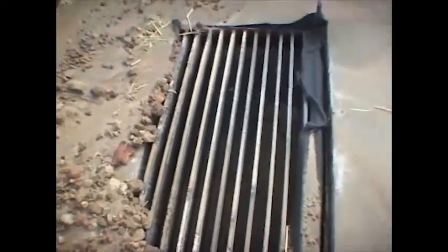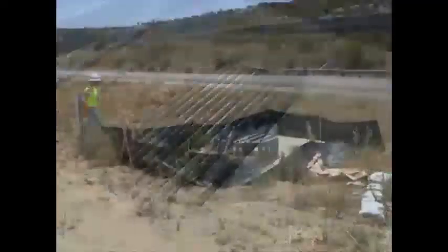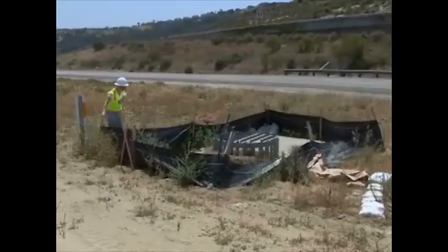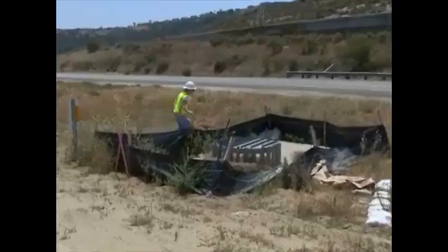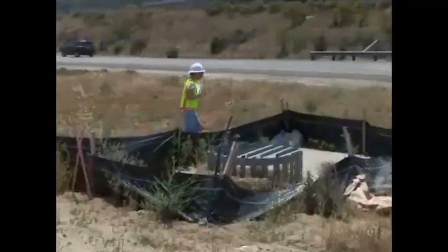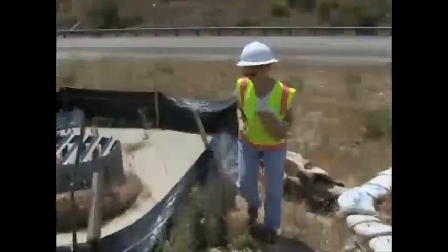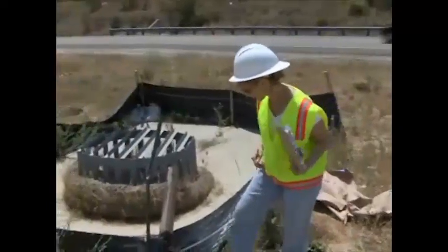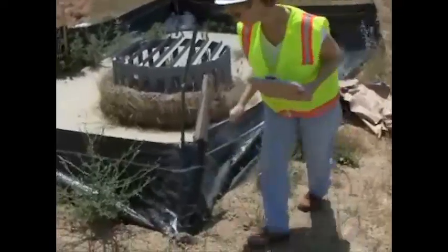If accumulated sediment has reached 1/3 the holding capacity of the device, then make a note of it and ensure that it is removed. Check and ensure that the stakes are securely driven into the ground and are in good shape, not bent, cracked, or splintered, and are reasonably perpendicular to the ground. Check fences and ensure that they are repaired or replaced when damage is noted. Check barriers for broken or torn bags.